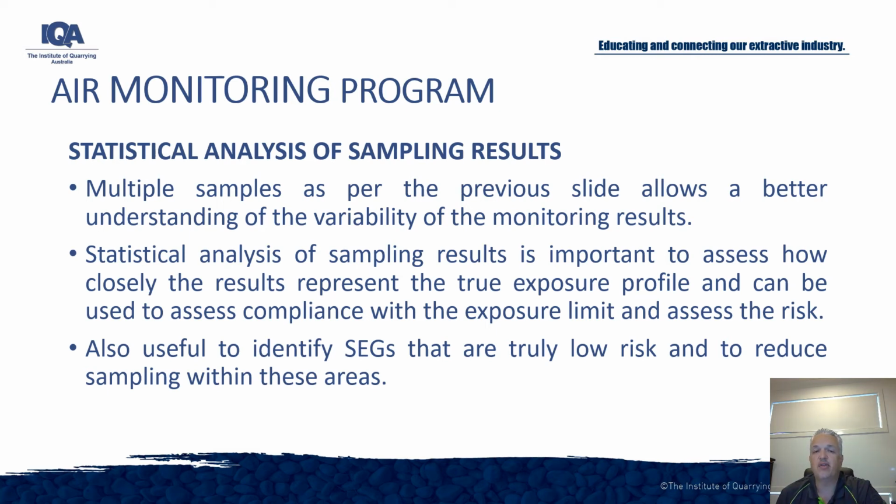It's also useful to identify the similar exposure groups or SEGs that are truly low risk and to reduce the sampling in these areas. If we've identified a very low risk, we can reduce the sampling regime to every 2 years or every 3 years and still be confident that we're not exposing our people.